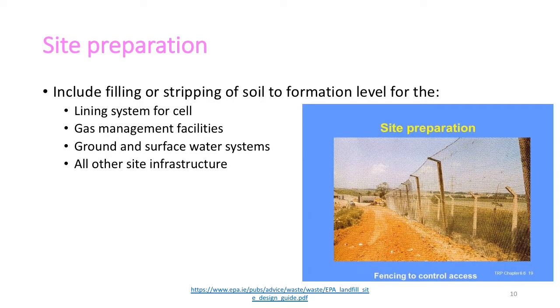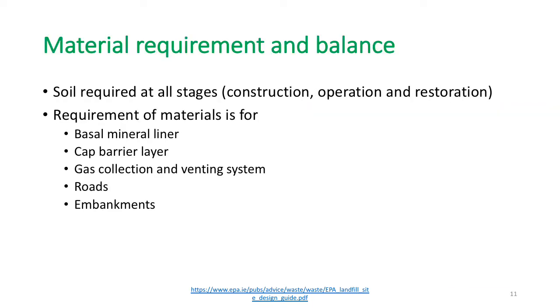Site preparation. For different activities, the landfill site is prepared, such as a lining system for cell, gas management facilities, ground and surface water systems, and all other site infrastructures. Material requirement and balance. Material such as soil is required at all the stages such as construction, operation and restoration.